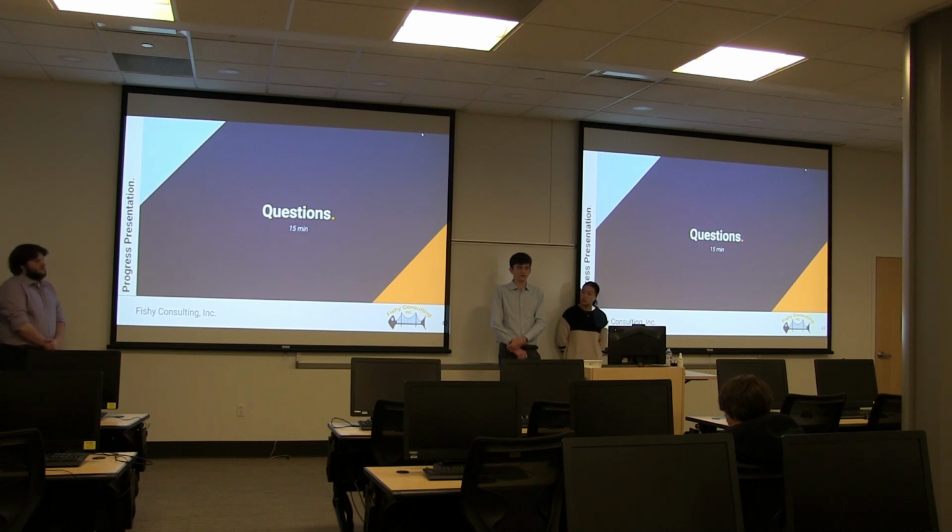I think in 22 there's a lot more that's already been factored in, so it may be at just 1.0, and then 16 is at 1.6. That's correct, yeah. That's why you have the hazard tool, and so the multiplier is 1.0 in 22 versus like 1.6 in ASCE 16.